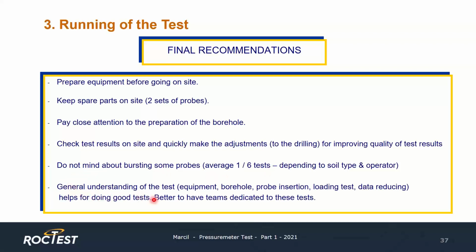And finally, a general understanding of the tests is a good thing. From how the equipment works, how to make the borehole, to how the probe is inserted, to how the data are reduced. If you have a general understanding of that, it will help to be successful. And also, it's good to have teams that are dedicated to the pressuremeter tests.